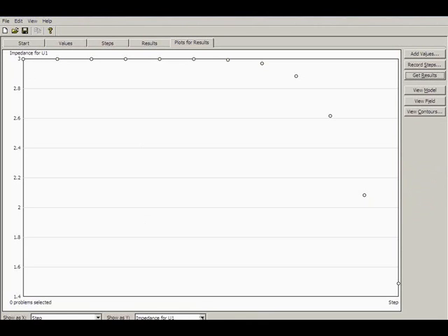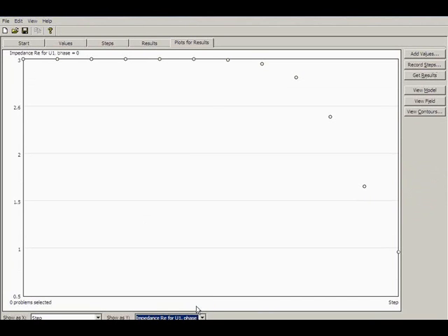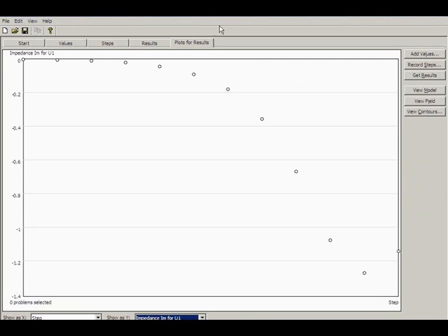This is the magnitude of the impedance as a function of frequency, also known as a Bode plot, along with the real part and the imaginary part of the impedance. Now, if we plot the real part of the impedance versus the imaginary part, what we'll have is a semicircular type of plot in the complex plane, and that is a Cole-Cole plot.